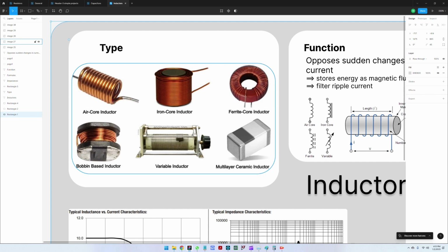This is an air core inductor here. You can see that the coils don't have any core, any ferrite core or any ferromagnetic core here. So the current goes through here. All these wires are isolated from one another. So for example, if the isolation of some of these wires would break in mounting or something, it will cause a short circuit and would damage the inductor, and the inductance will go down quite fast.